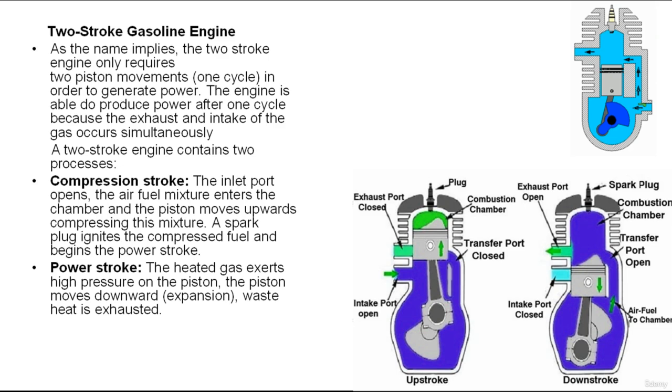So although the 2-stroke cycle engine is simple in design and lightweight because it lacks a valve train, it has not been widely used in automobiles. It tends to be less fuel efficient and release more pollutants into the atmosphere than 4-stroke engines. Oil is often in the exhaust stream because these engines require constant oil delivery to the cylinders to keep the piston lubricated, and some of these engines require a certain amount of oil to be mixed with the fuel.